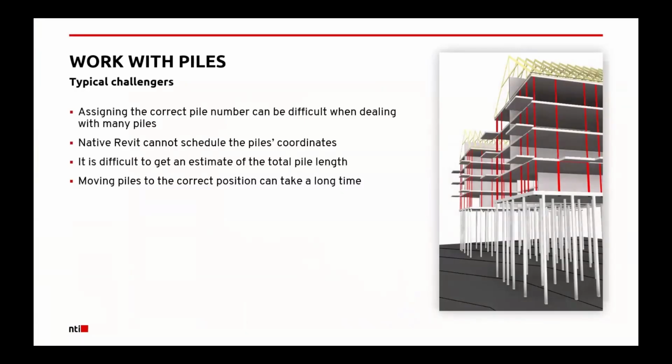NTI for REVIT Structure solves several challenges with piling, like assign each pile a unique number. You can schedule coordinates and cut off levels for each pile. It's easy to extend the piles toward the bedrock. You can easily move piles relative to walls or grids.